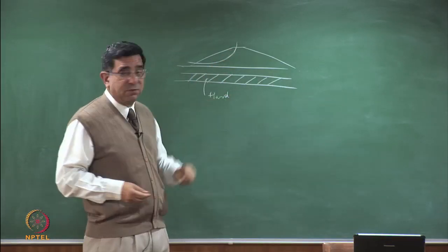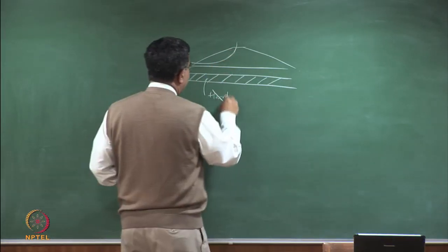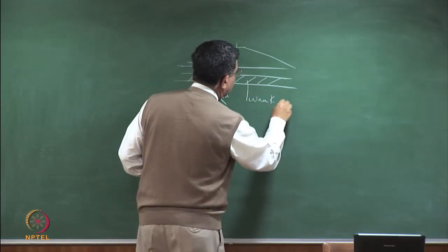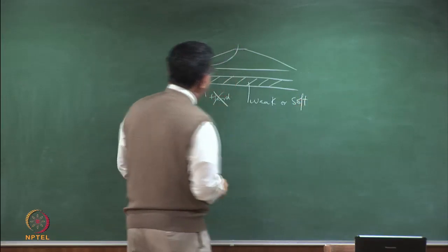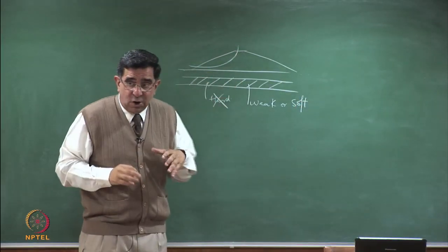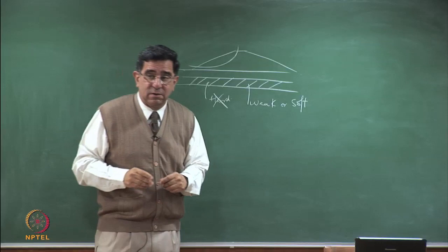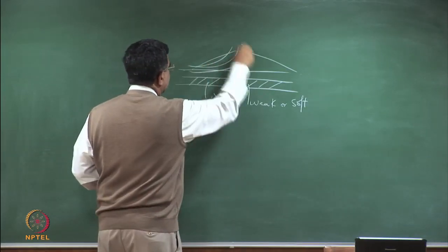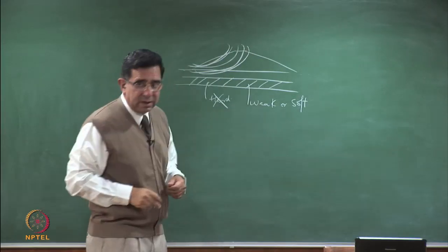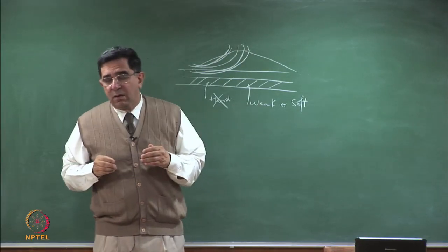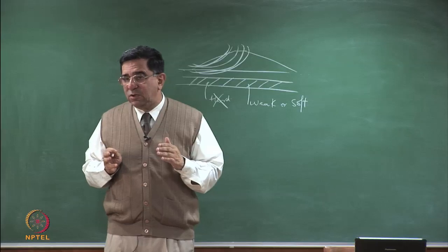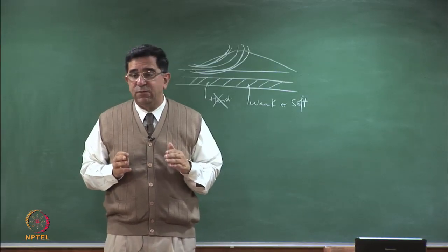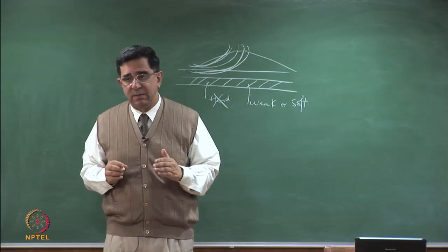So if I have a weak or soft surface here, then this failure surface might be drawn towards it, may not necessarily be the critical failure, because you are doing a lot of circles. As we said, to find the critical factor of safety, you will have so many circles which will be done. So which is the case in which you definitely get weak surfaces, and you have to try for straight line analysis as well.